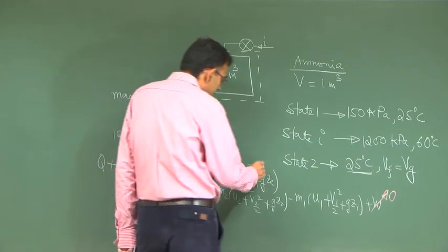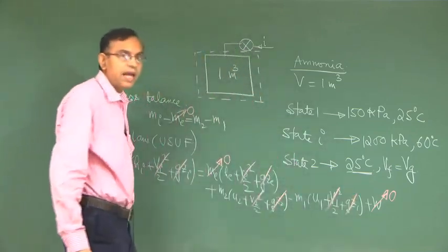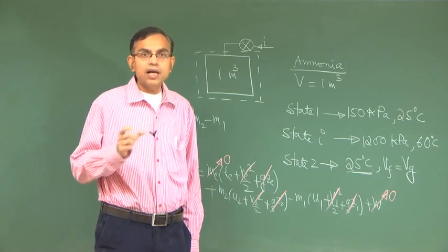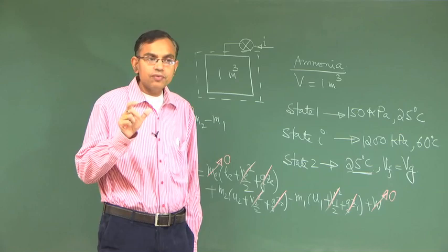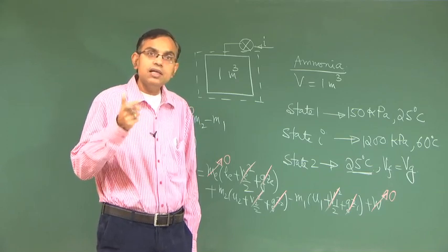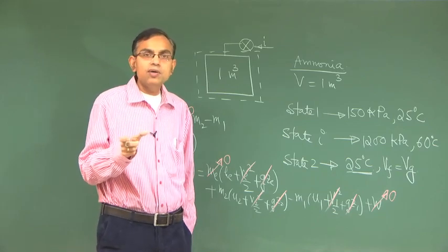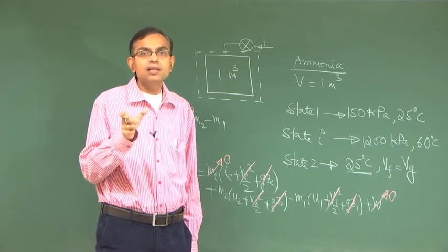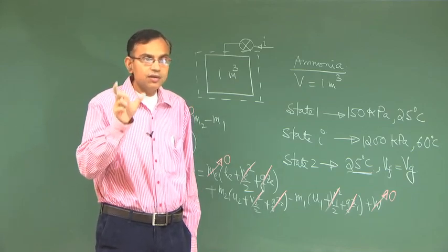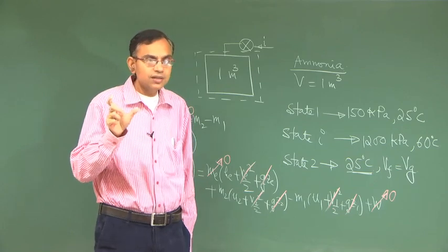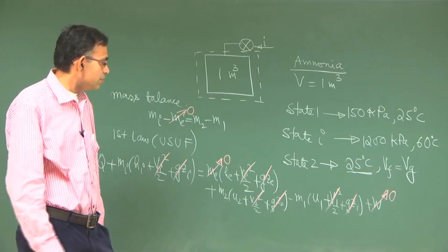You will have negligible changes in kinetic energy and potential energy. For most of the problems it is like that, but sometimes your examiner tries to make sure whether you are very alert. In some problems kinetic and potential energy changes may be important. So, you look into the problem statement first and see whether there is any hint that some of those terms may be important, check it very clearly. If there is no hint like that, you can safely neglect changes in kinetic energy and potential energy.